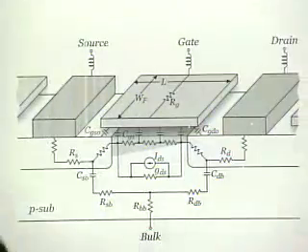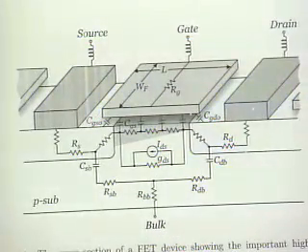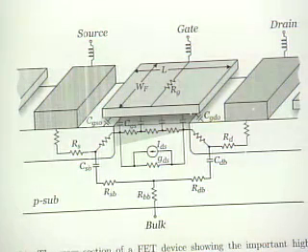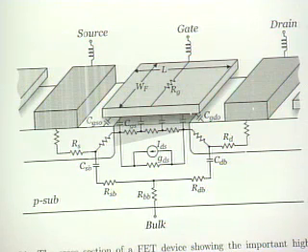So this is a more complete model of a FET, and it tries to include all the loss mechanisms in the device. The reason we're doing this is because when you actually sit down and think about how much power you can extract from a device, it all comes down to the losses in the device. Partly it's the omega t of the device, right? We saw that even in the simple amplifier. But the other terms really came out to depend on the inherent resistances in the device. So if we can minimize these resistances, we can maximize how much power gain we can get out of the device.